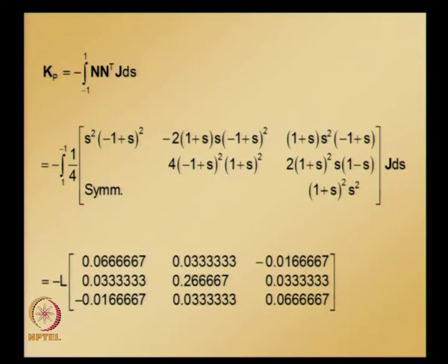The evaluation of this integral becomes simpler because J is constant. If J is not constant, then the integrand is going to be more complicated, and evaluating these integrals is going to be complicated, where we will adopt numerical integration techniques, which we will discuss later. So, these are the element equations for element 1.